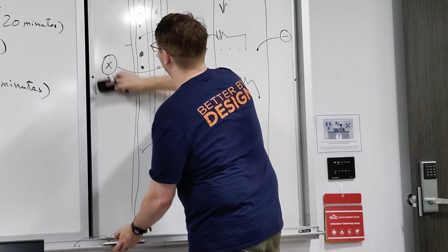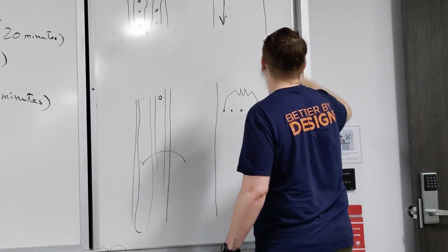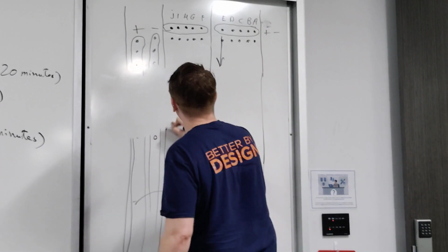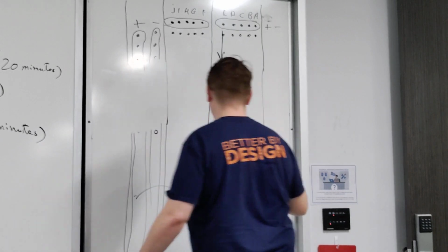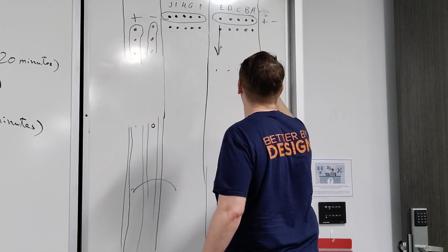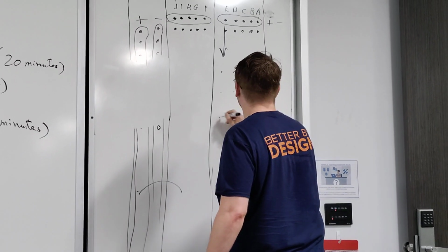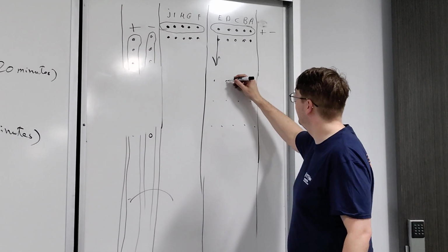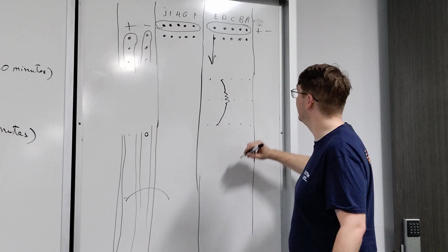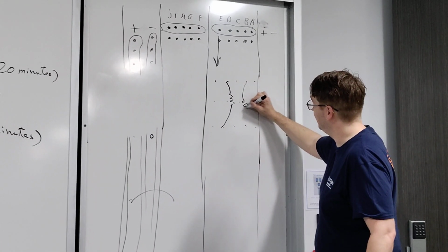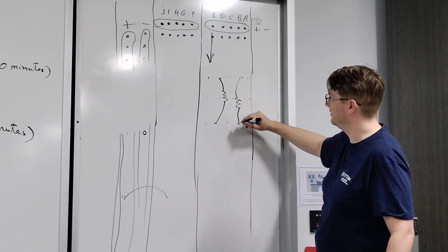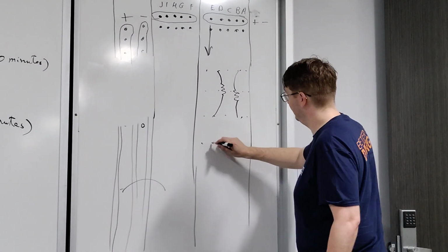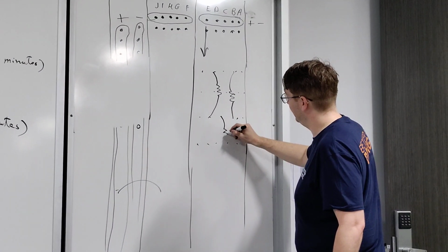If we want to do something a little more complicated, that's fine. So I want 2 resistors in parallel. For example, I could put one resistor going between that hole and that hole, and then a parallel resistor would just be doing the same thing, going from the same row to the same row, and they would be in parallel. If I want these 2 parallel resistors and then I want a series resistor afterwards, I just hook it up and move to a different row.